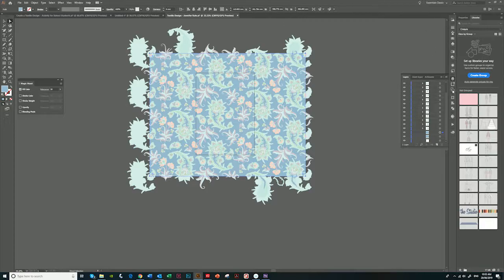So if we come over here to the artboard, you can see we've got an artboard here, and that is this one here, this black line showing the artboard, which is the A4, but we want it to be this one here, so we just created a shape for that. Now if we come to the menu in the artboard and we go convert to artboard, can you see we now have a second artboard, and this now has the black solid line.